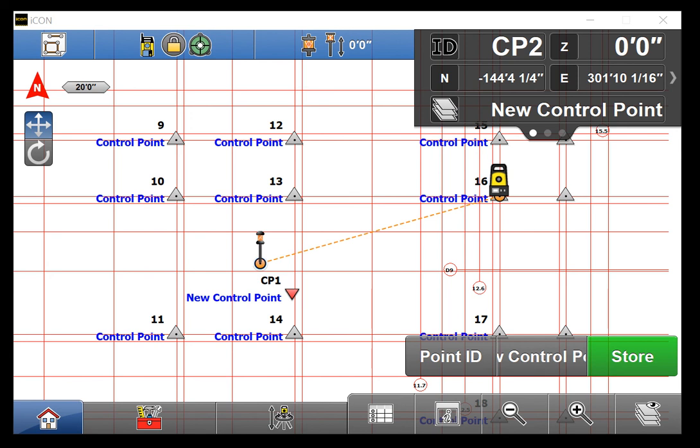At a minimum, when setting a new control point, always re-level your total station and complete a new setup anywhere. Make sure your angle is as wide as possible, and don't measure your new control point further than your longest setup anywhere control point. If possible, try to do this as seldom as possible and rely on the supplied control from the GC as much as you can.